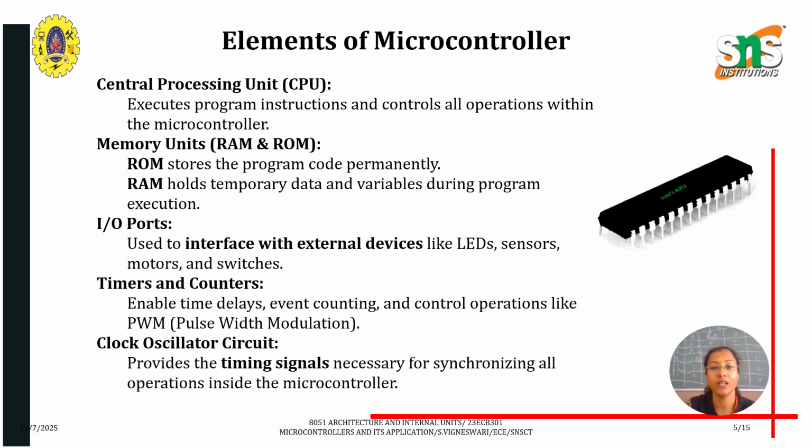Next come the I/O ports, input and output ports. These are specifically used for interfacing with external devices like sensors, LEDs, switches, stepper motors, and interface circuits also. Timers and counters are specifically designed for elapsing the time delays necessary for synchronization of the operations. They are also used in control applications like pulse width modulation circuits and waveform generation.